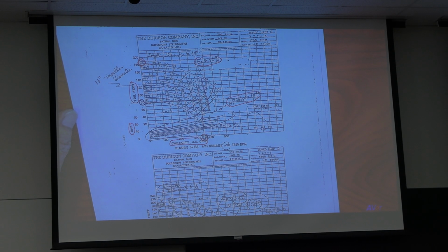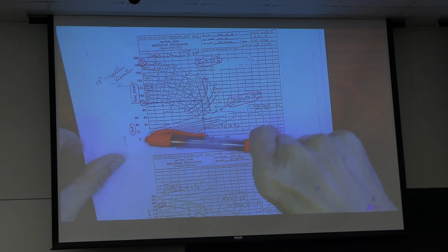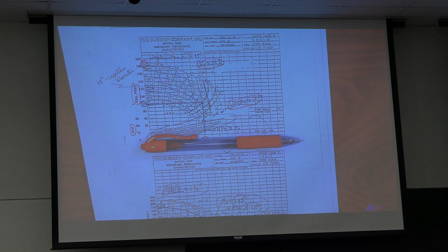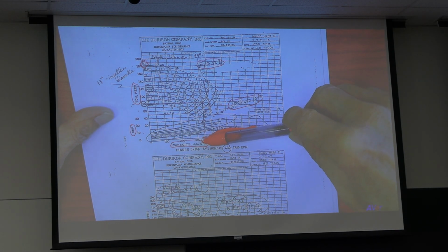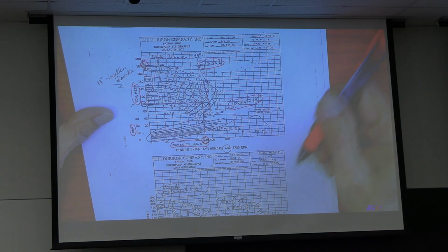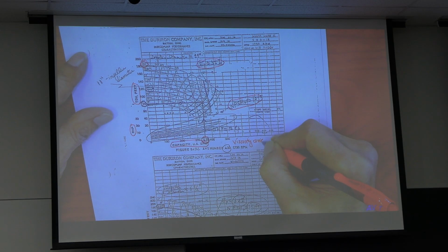Water. For pump curve. Pumping rate. If you have a viscous liquid, 100 centipoise, pumping at 350 gallon per minute, do you reach 350? You cannot read it that way. You must do viscosity correction.